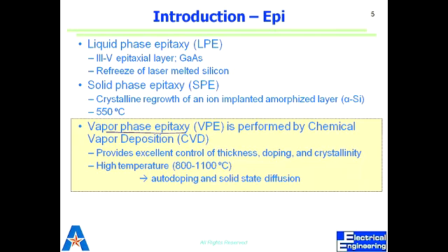High temperature, and it gives us a very good uniform layer of epitaxy. It has its own issues. High temperature causes the dopants to misbehave. Two ways: it's called auto-doping and diffusion. Of course, you know diffusion, where things travel, they would get diffused even further in the devices.